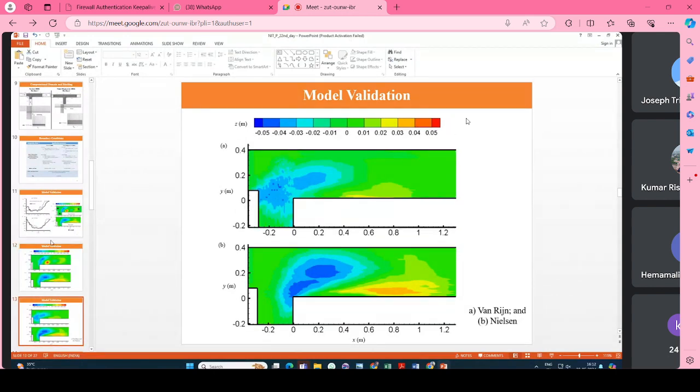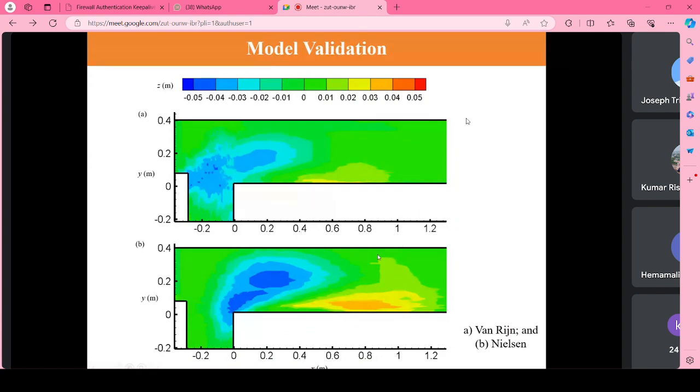Right. Now, I have shown you the results using the MPM equation. I have also tried a different bed load transport equation, the Van Rijn equation. You might have heard of it; it is very popular, similar to the MPM equation and the Nelson formula.